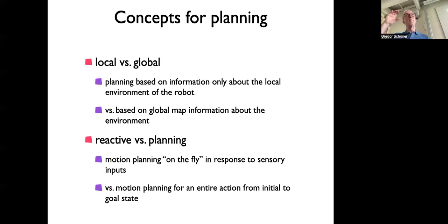When you do global planning, that requires more. You were hinting at SLAM, and I'll talk about SLAM later. That is, you then also need to know where you are in that history. Relative to that history, you have to estimate your ego position, and that is actually also a problem. This is also pretty much solved, I would say, but it's a problem. So conceptually, it's not the same. Conceptually, you can do local planning and use history just to stabilize the sensor information that you have, like a Kalman filter.